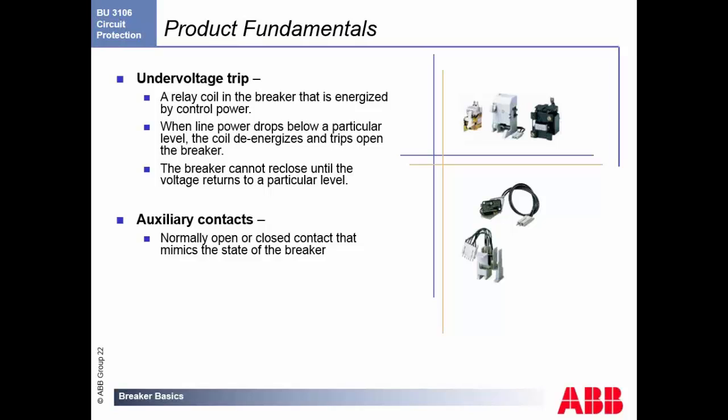We have auxiliary contacts so that there are ways to bring the switches to disconnect the breaker or open the breaker without actually going to the breaker. Again, a very nice safety feature. You can have it done on automatic, say a time clock. So on a building that you want to shut down the breaker on, say, a Wednesday at 6 p.m., if you have a time clock that can send out a 24-volt signal to our breaker, these auxiliary contacts will accept that, a dry contact closure, see that now you want to open the breaker, and it opens.